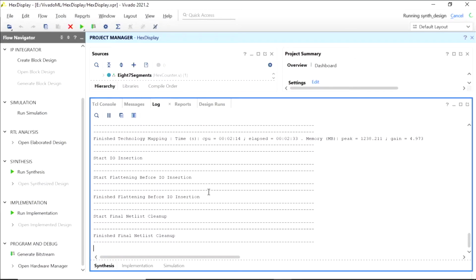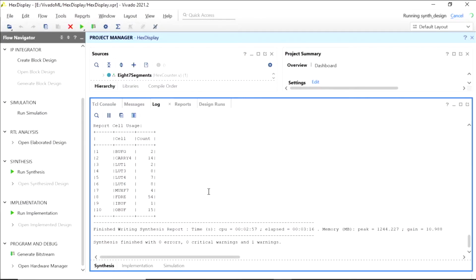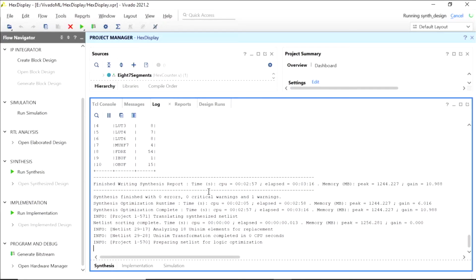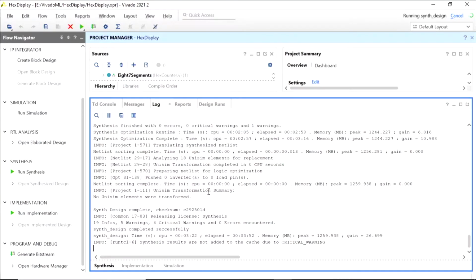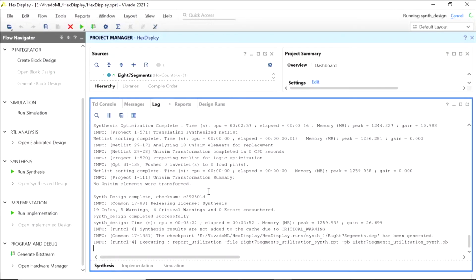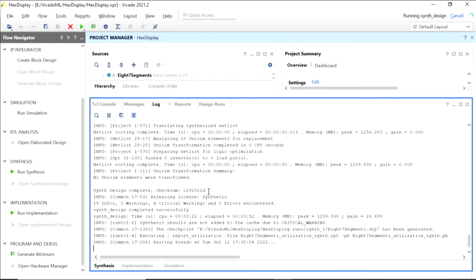So on the advanced end, I'm working on making my own processor. Currently, it's 24-bit. It's got 32 instructions. All the favorites like jump on carry, clear. I'm using jump because I have a 24-bit instruction, and I've got like 18 bits left over, 19 bits left over. So branches stop making sense. Relative branching from the program counter.